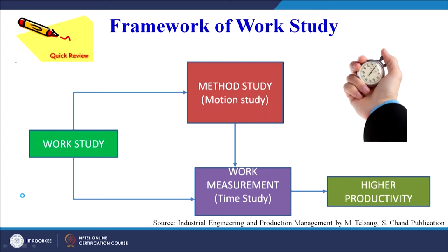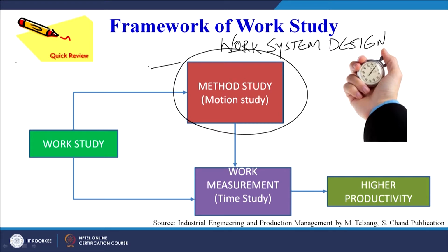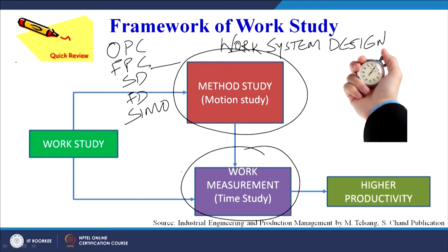Now, this is the framework of work study, or we can say, as our subject title goes, the work system design. The work study has two major components. One is the method study, which we do through the operation process chart, flow process chart, string diagram, flow diagram, and SIMO chart. All this we have already discussed in the last 4 weeks of our discussion. Now, our focus primarily is on work measurement, or we also call it time study.